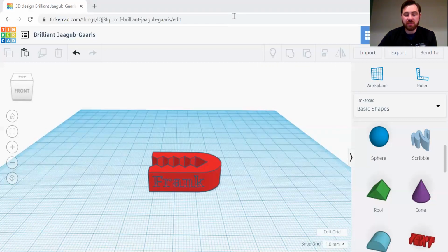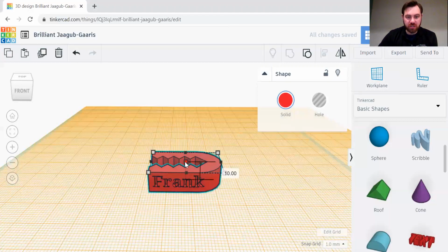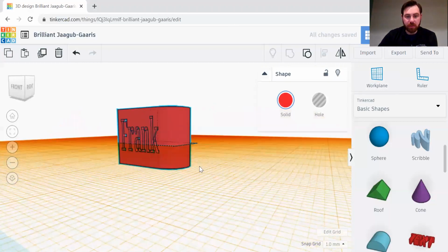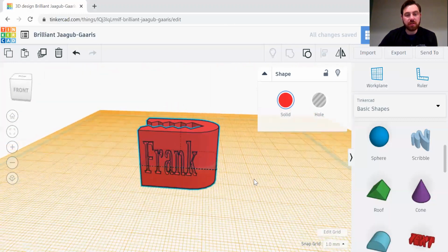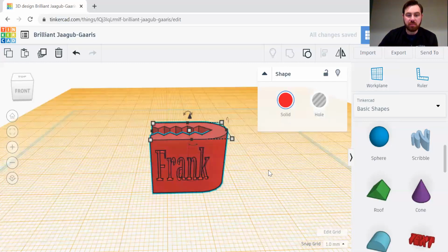Yeah, so there's another question here too, guys. If you change the height of the clip, will the new Workplane change along with it? Great question. Let's take a look. If we pop on a new Workplane right on top, and then we change the height, oh, it stays at the original spot that you placed the Workplane. So if you realize, oh, you know what, I wanted to make it taller, you can do that. You just have to go back, grab another Workplane, and put it on top.